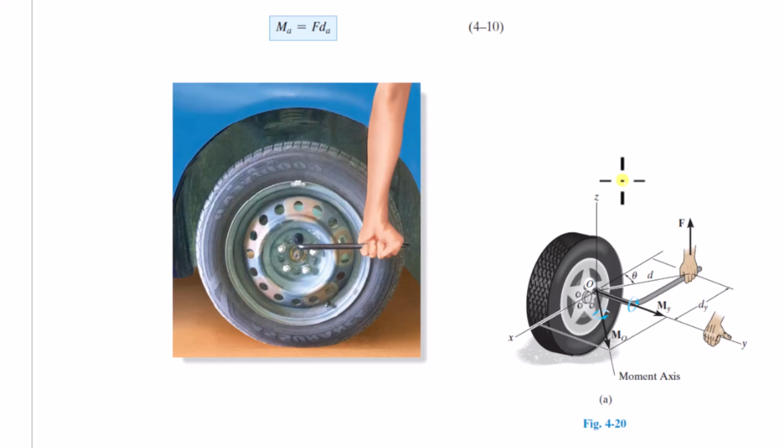but if you want to do this manually, the whole idea is you need to find the distance that's perpendicular to the line of action of the force and perpendicular to the axis that you're interested in. So it's perpendicular here, and then this is perpendicular here, right? Like, you can extend this. This is D, perpendicular here and there, right? So if you extend this line of action, you wouldn't do this, right? So if you do force times that perpendicular distance, that's the moment of the force about that axis.